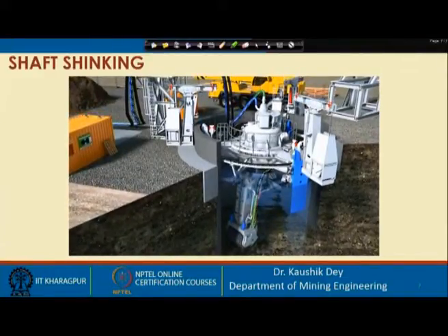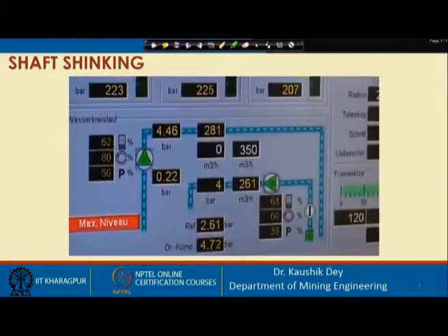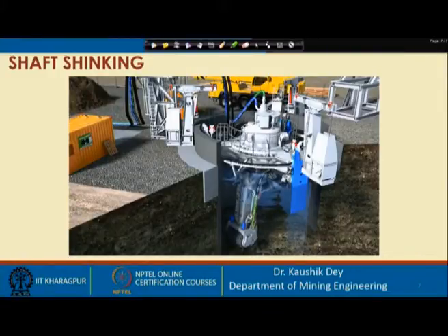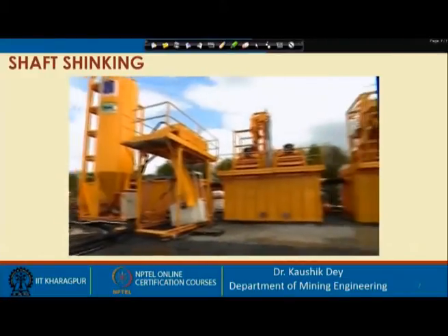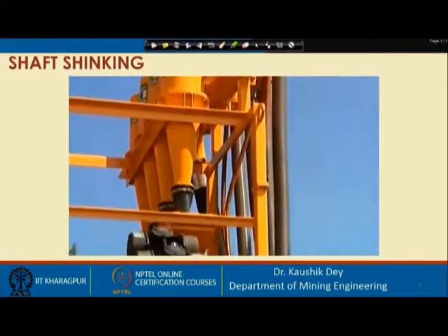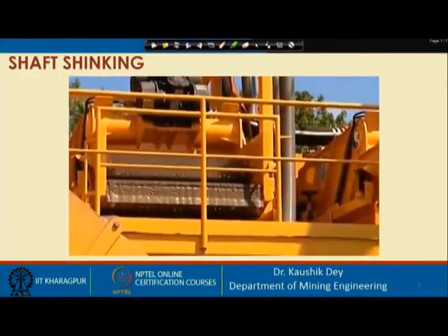The cutter drum basically cuts and crushes the material. The cut material is crushed to a granular size that can be handled by the integrated centrifugal pump and sent to the settling tank. In sticky ground conditions, an additional high-pressure feed line can be used to clean the cutting drum. The separation equipment is selected to suit the local soil conditions, and then the fresh water may be recirculated.